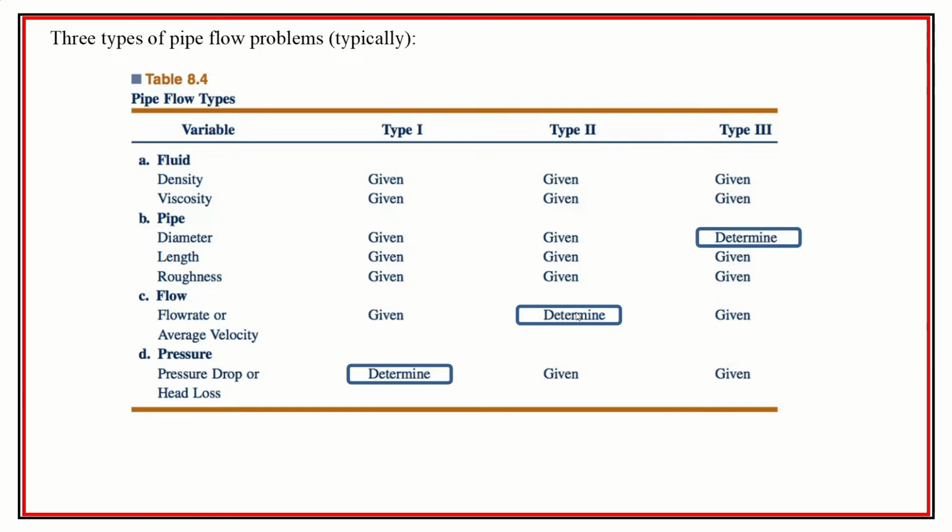That's actually a more difficult type of problem because we don't know what the velocity in the pipe or through the fittings is, and therefore we're not able to get what those head losses are going to be. So we need to do an iterative process here. And instead of that approach, it might make more sense to put together some type of computer program.